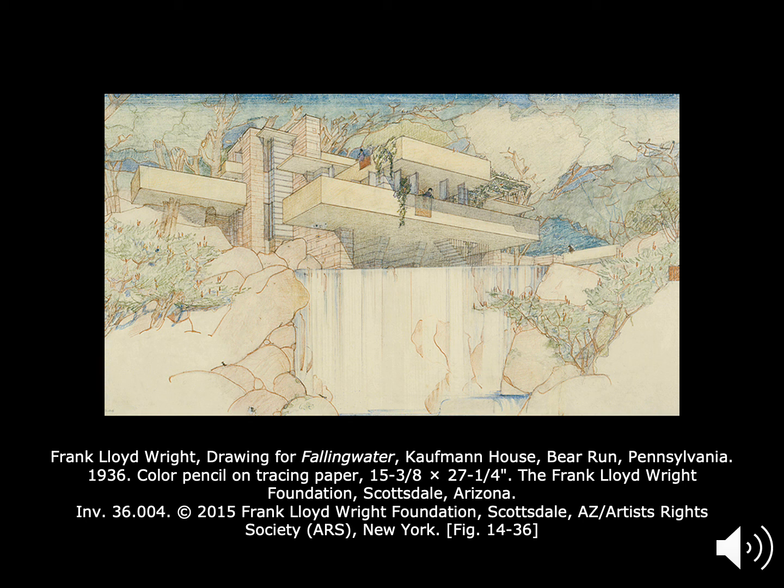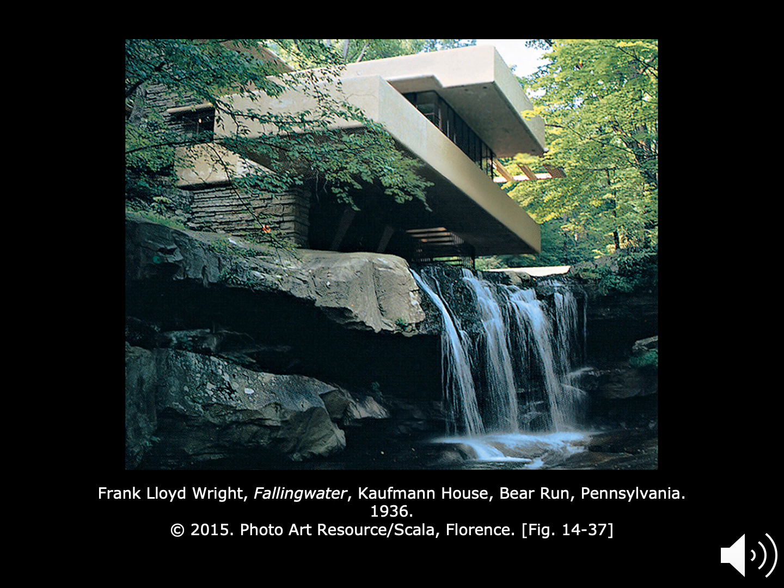Thinking through architecture, Frank Lloyd Wright's Fallingwater. The first drawings for this famous house weren't completed until 2 hours before Edgar Kaufmann made a surprise call requesting a draft. The house was wedded to its site, a hillside atop the Bear Run stream. Kaufmann, as well as the contractor and engineer, did not trust Wright's plans for reinforcing the concrete for the cantilevers. They put twice as much steel as Wright called for, and it caused the main cantilever to droop.